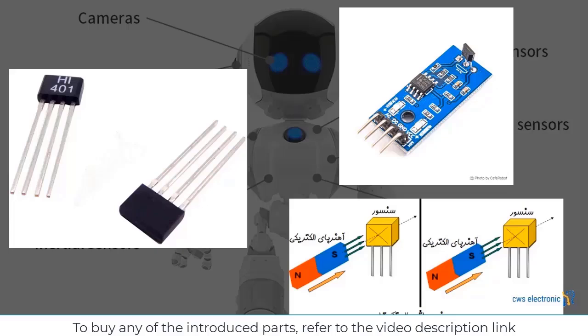For example, you could imagine that as the robot gets closer to a source of magnetic field, it can detect this approach. Of course, you can even build different devices with a Hall effect sensor, for example, if you want to know what's actually inside the wall. Is the wiring, for example, voltage carrying? In fact, this sensor is a magnetic field sensor. An electric wire that is buried inside the wall creates a weak magnetic field when there is electricity inside it.